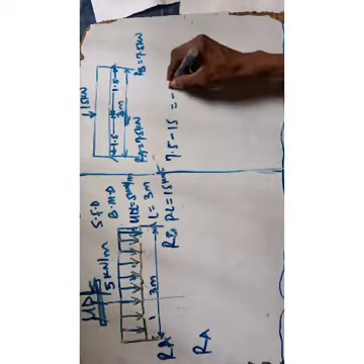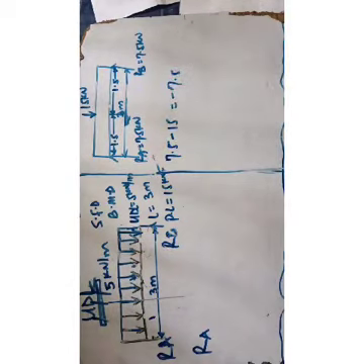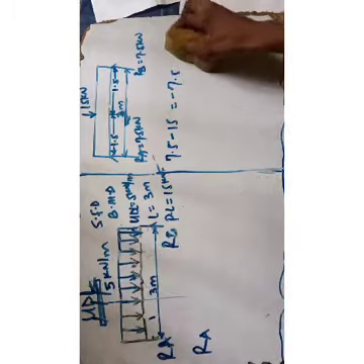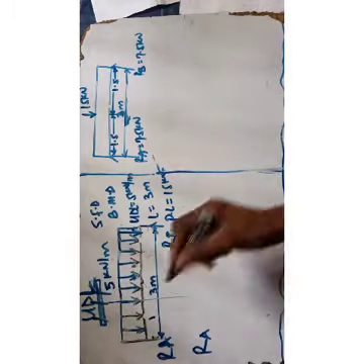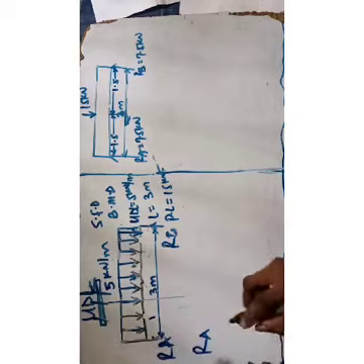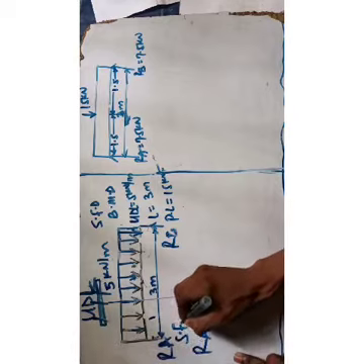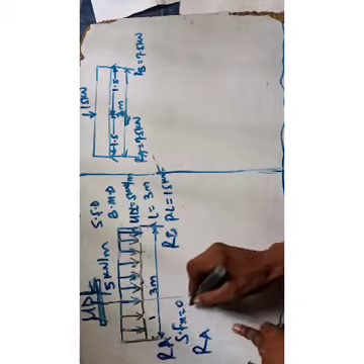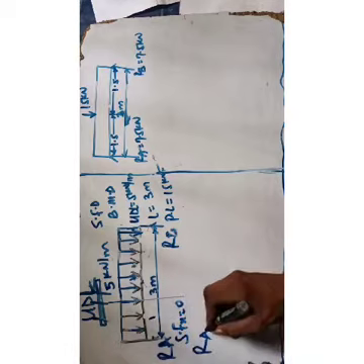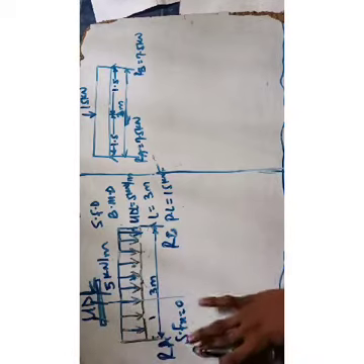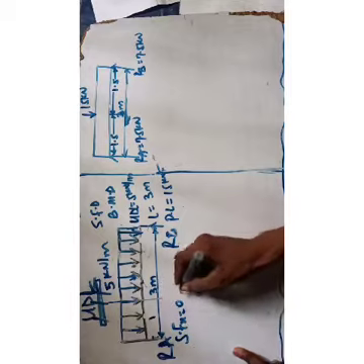Okay, and that'll be minus 7.5. But for UDL, you will not just stop here, you will not just start there, rather you would start from when x equals 0. So shear force when x equals 0, you have it as just the force acting here, and that will be equal to Ra. When x equals 0, your shear force is equal to what?